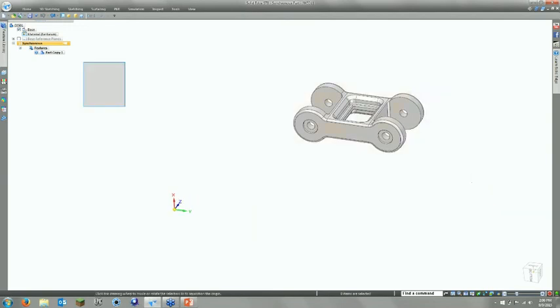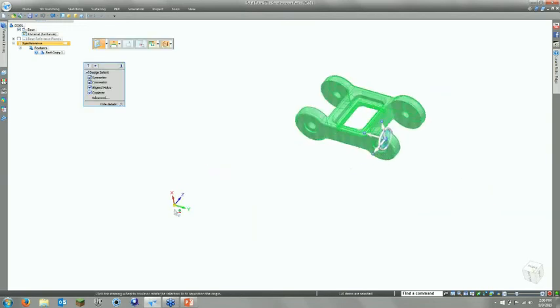Something I'm going to do is move this entire piece of geometry back to my coordinate system. A lot of the symmetry and the relationships are built into the coordinate system. So I'm going to use a simple tool, the steering wheel. And what I'm going to do is actually use a key point. I want to say midpoint. I'm not sure which edge I'm on. It doesn't really matter.